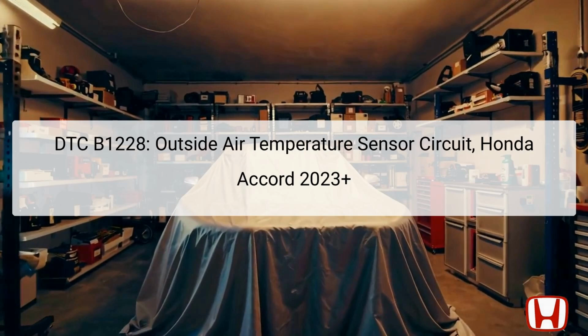DTC B1228, indicating a short in the outside air temperature sensor circuit, typically affects the Honda Accord 2023 and newer models. This error arises when the input voltage from the outside air temperature sensor doesn't meet the specified range, leading the climate control unit to identify an issue, consequently storing the DTC.